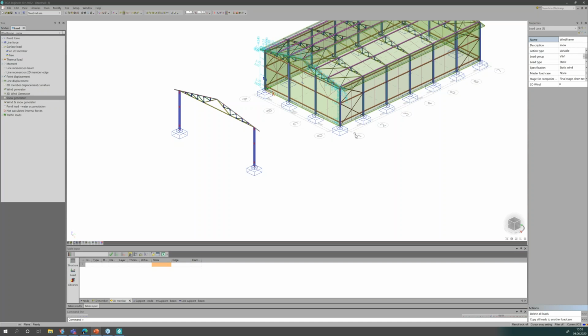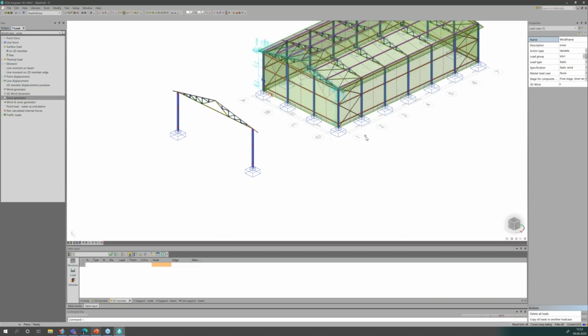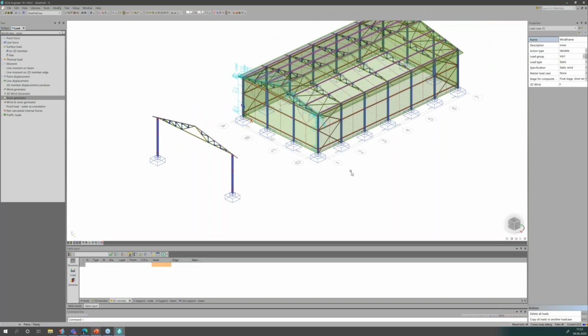The circular ones are a bit difficult, and what we are doing in the wind load generator is that we are identifying the structure according to the categories, let's say, which are in the Eurocode, and in the Eurocode you can find, let's say, square buildings with dual pitch, mono pitch, or some flat roof, and that's mainly it.